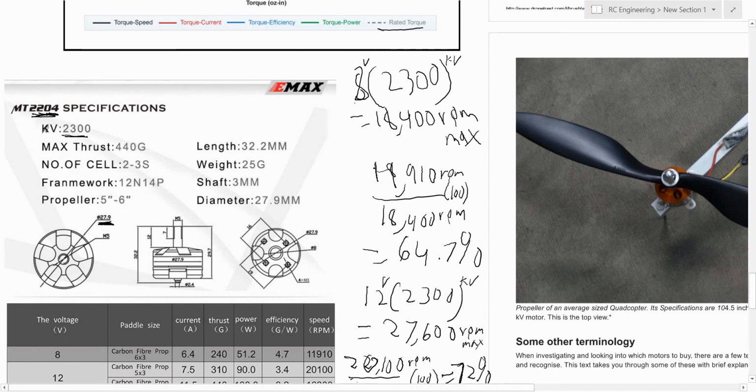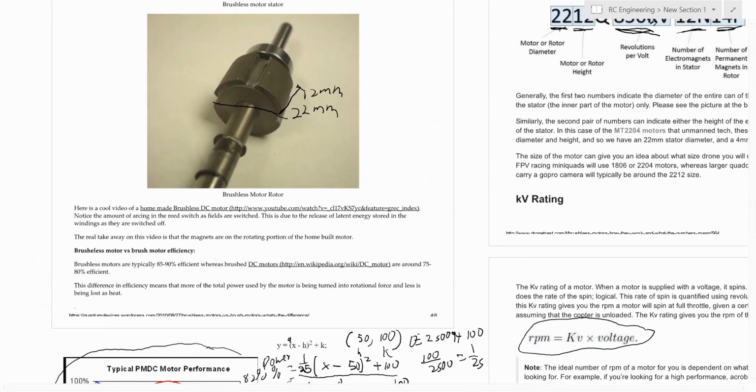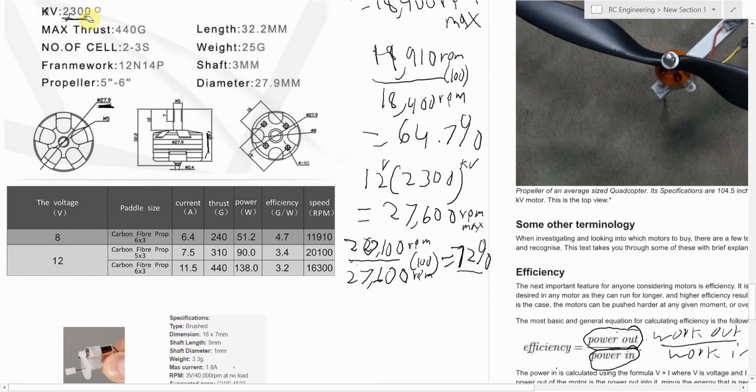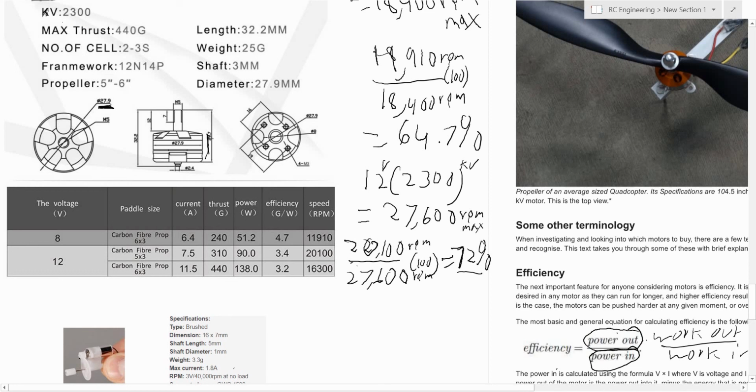Then it says 04, and obviously it's more than 4 millimeters tall, so that must mean that the rotor inside is 4 millimeters long. Then we see our kV is 2300, so obviously we're going to use our intuition and assume that we don't want to multiply that by 1000, because that's not going to be right.